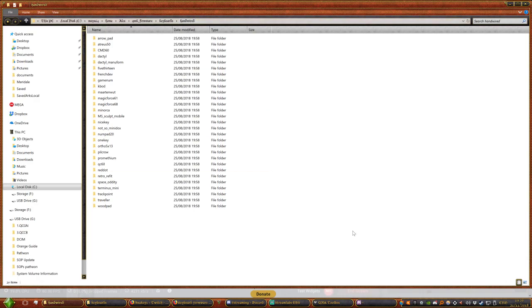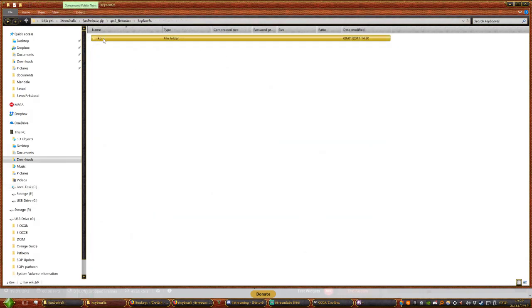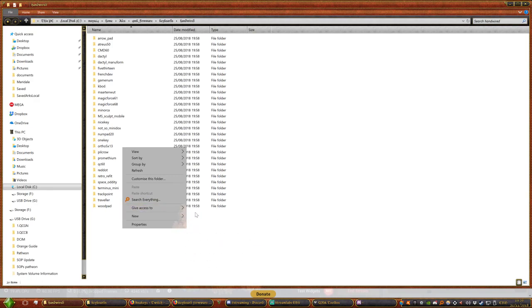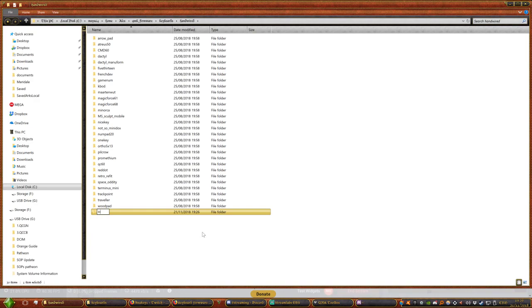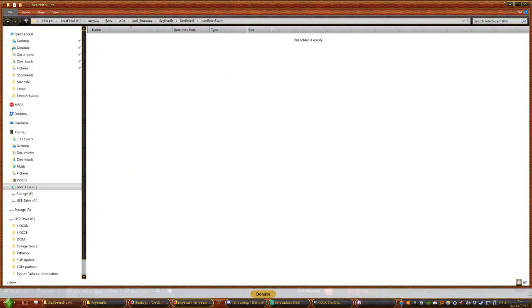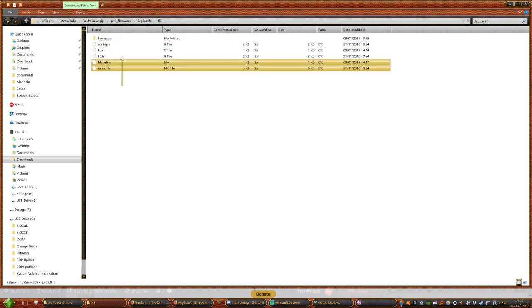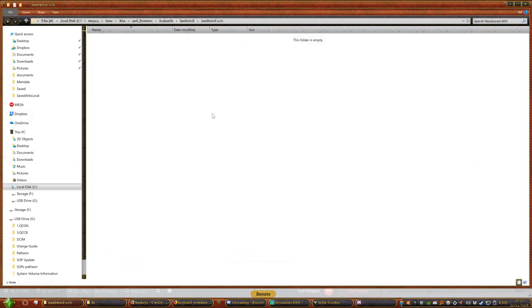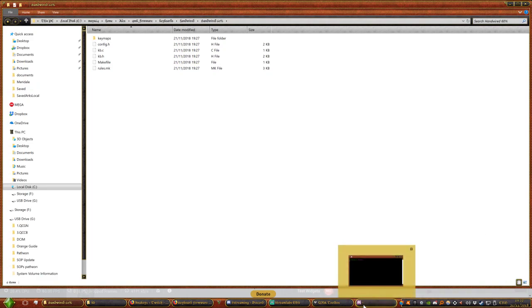So then what we need to do is we need to then copy this KB folder into the QMK firmware folder. So I'm going to choose keyboards, Handwired, and then get a new folder in here. So this is going to be Handwired 60%. So there it is. So then now I'm just going to copy all of these, because these are the files that we need, and put them in that Handwired 60% folder. So the reason why I've done this is that when I go to compile, this is going to know exactly where to fetch the files.